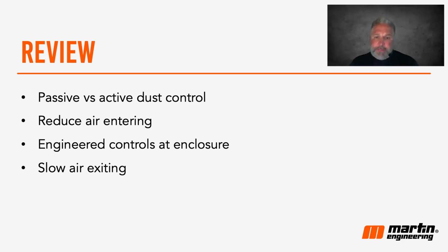So let's review real quick. There's passive, there's active. Passive systems are less expensive. They don't require water. They don't require electricity. It's steel, rubber, grinding, and welding. No specialized maintenance, no additional cost. Reduce air entering. If you can give yourselves a fighting chance of reducing the air that exits that enclosure by reducing the air that enters the enclosure, you're going to be in a good spot. So reduce the air that enters that enclosure.